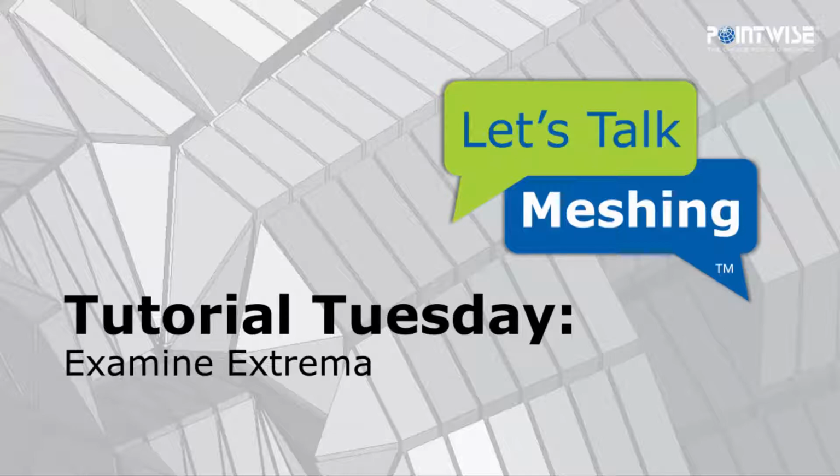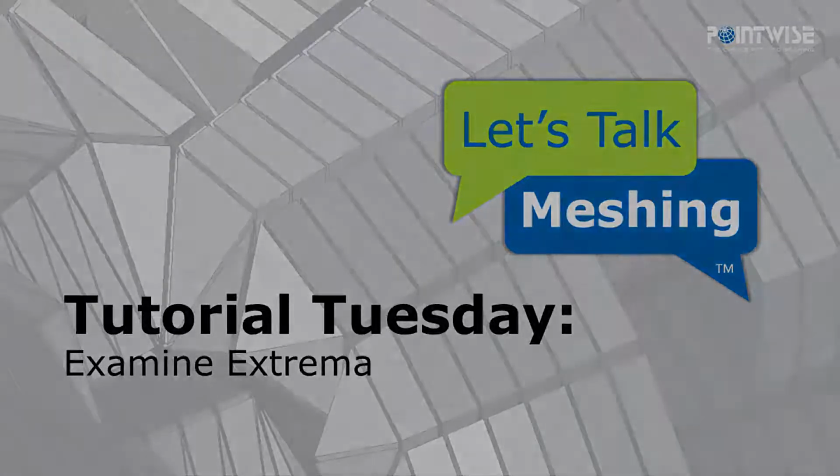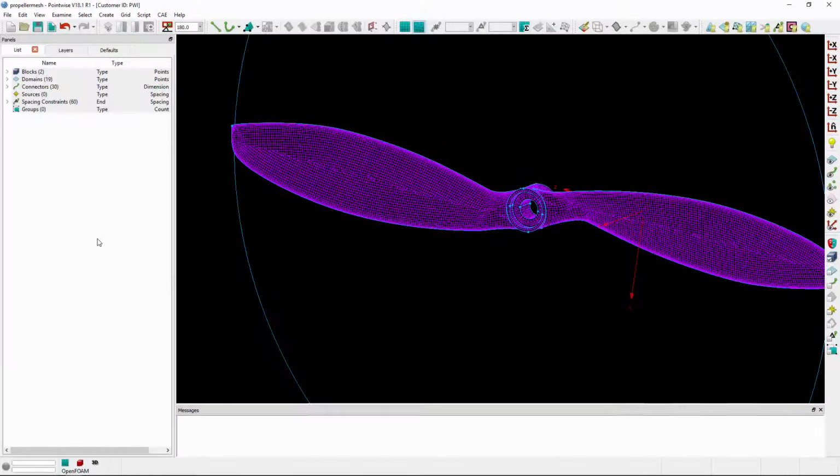In today's video, we're going to cover the Extrema tab within Examine. So the Extrema tab provides tabular information about the minimum, maximum, and average function values that you're examining, including their location. And you might say, well, I can get most of that information from the color bar within Examine, and you'd be correct, but the one thing you can't get is location information. Additionally, the Extrema tab is going to provide a mechanism for zooming to the minimum or maximum values for further diagnosis.